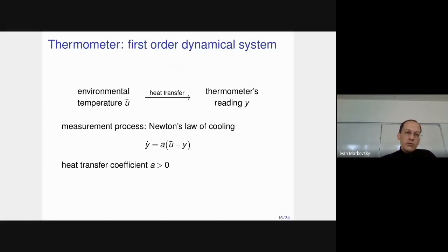And that means we have to do it adaptively. We not only estimate the value of interest Y, but also the model. And doing this in a classical framework would be the model-based approach. We first identify the model, and then we use the model for filtering. But using the direct techniques of data-driven methods, we can avoid the modeling of the process, namely getting the parameter A. We can directly predict the steady state value, and that's something new that I'll show you.